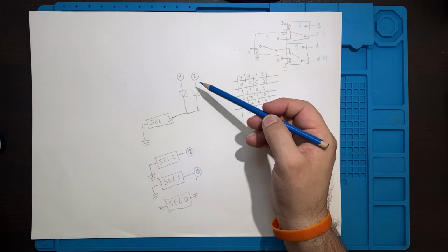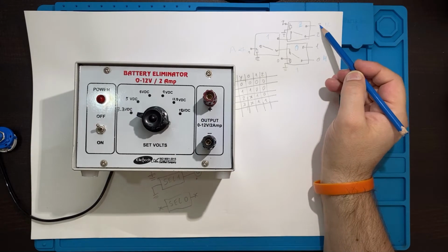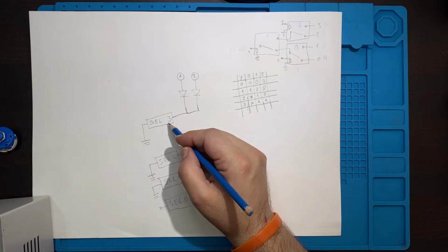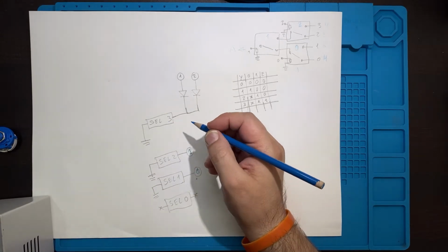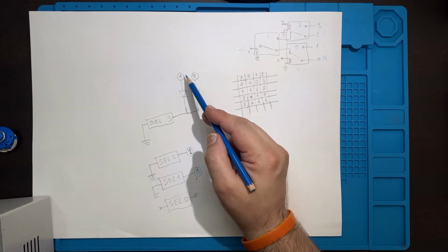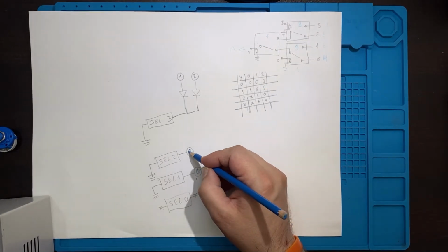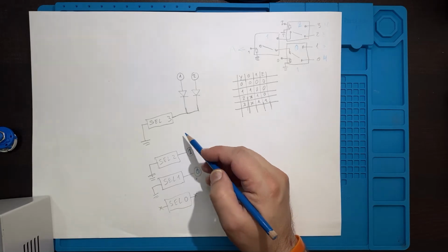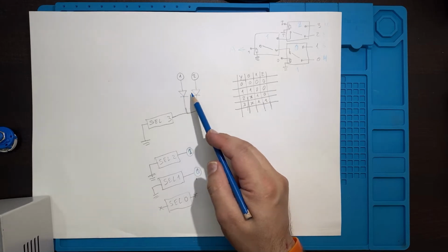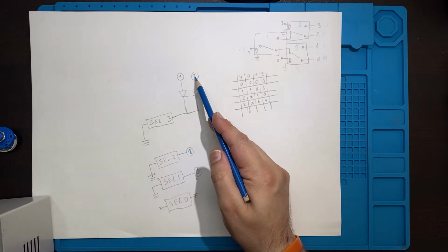The other thing is, at a specific point, for example, to select 18 volts, I need to select here number 3 to connect to 12. So when I have the selection type 3 here, I have 2 diodes connected to these so that I don't have to short 1 and 2, the coils together. Otherwise, if I select 1 and I didn't have these diodes, 1 and 2 would be selected whenever I select 1 or 2.